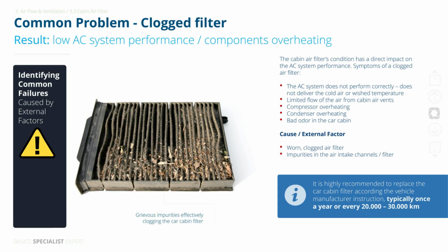A clogged cabin air filter chokes airflow, hurts AC performance, and can even overheat components. Dirt, debris, or a worn filter are usual culprits, so replacing it regularly keeps the system healthy.